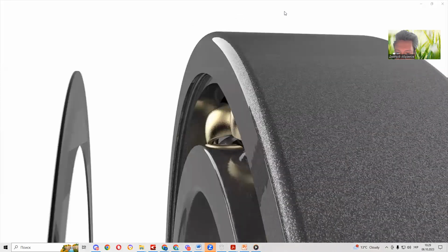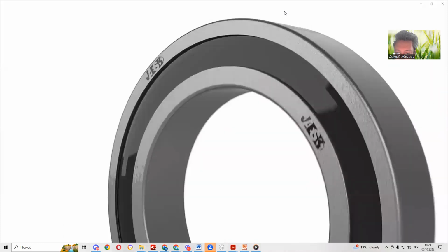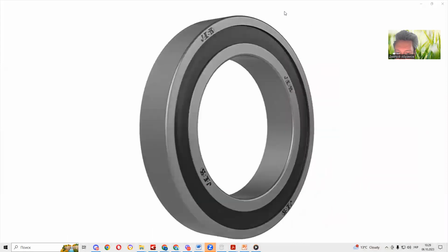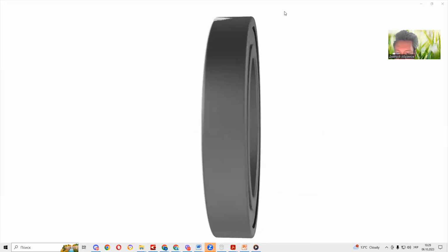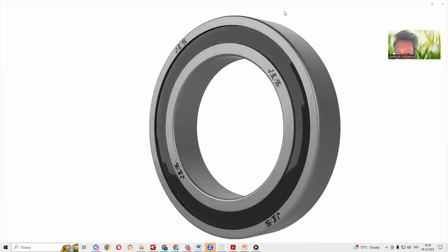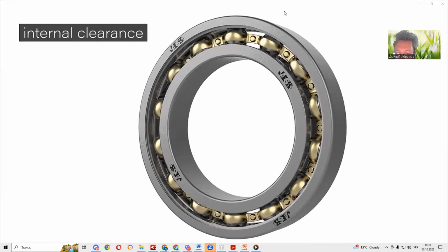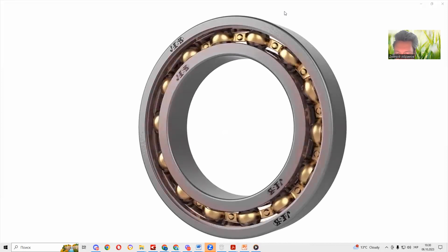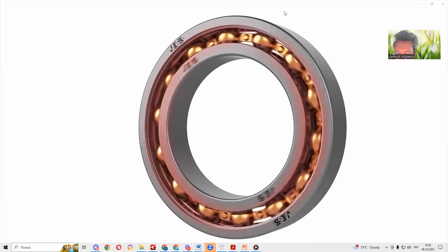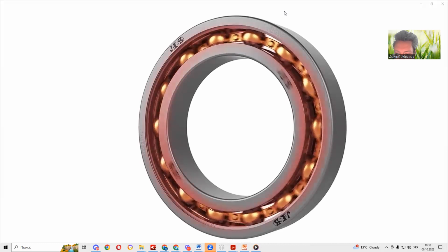They are placed in specific locations between the two rings so that they can protect the balls and the cage from external agents. At the same time, they can retain oil or grease inside the bearing, keeping it lubricated for its entire life cycle. In order to work correctly, bearings need a certain radial and axial clearance, so that when they reach the working temperature, their thermal expansion won't lead to over-tightening, which would cause the bearings to wear, or in the worst case, even a seizure.